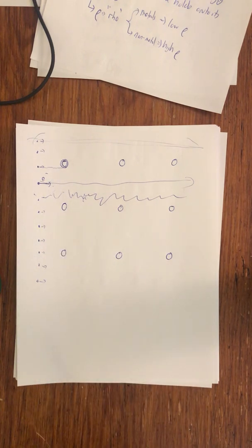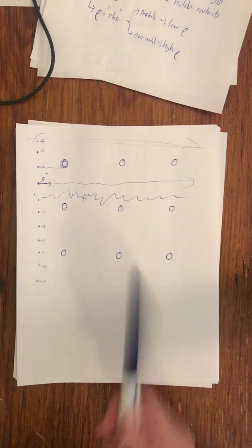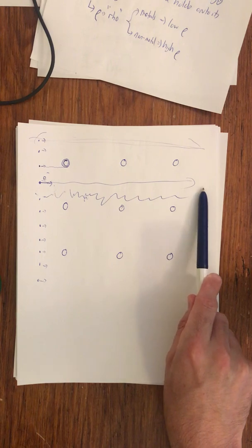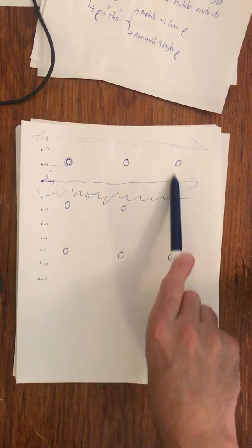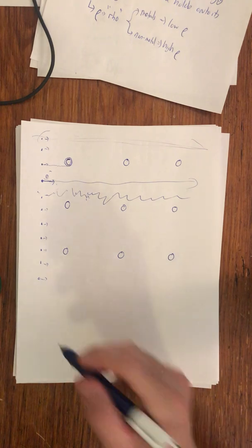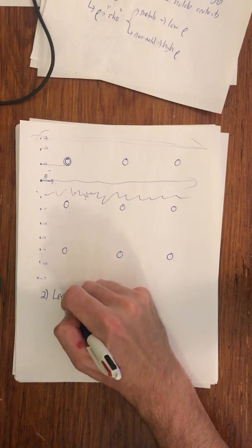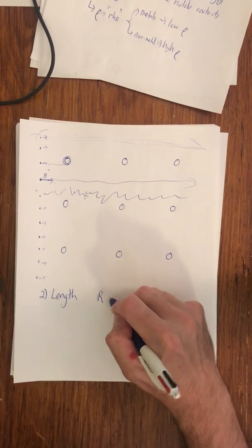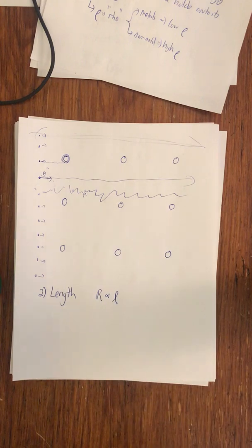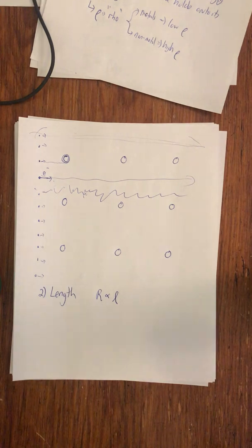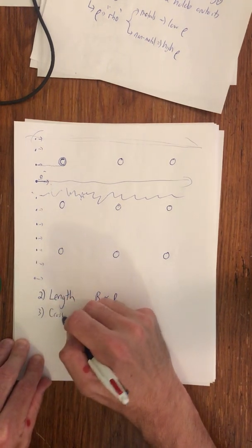Have you ever played the game where you try to walk down the hallway without bumping into anyone? Have you ever noticed that the further you have to go, the harder that is? It's the same thing for electrons. The further the electron has to go, the more likely it is to get pulled onto an atom because of its erratic path. And so we're going to say the next factor that affects resistance is the length of the path, such that the resistance is directly proportional to the length of the path, because the longer the path is, the more likely it is for the electron to get pulled back in. The next thing is going to be the cross-sectional area.